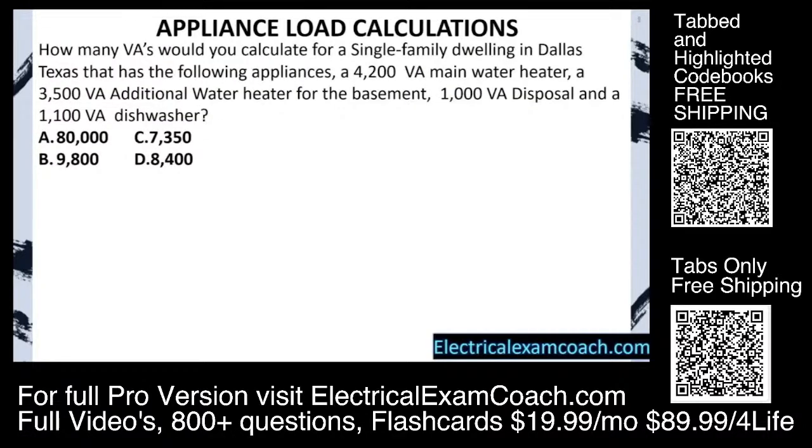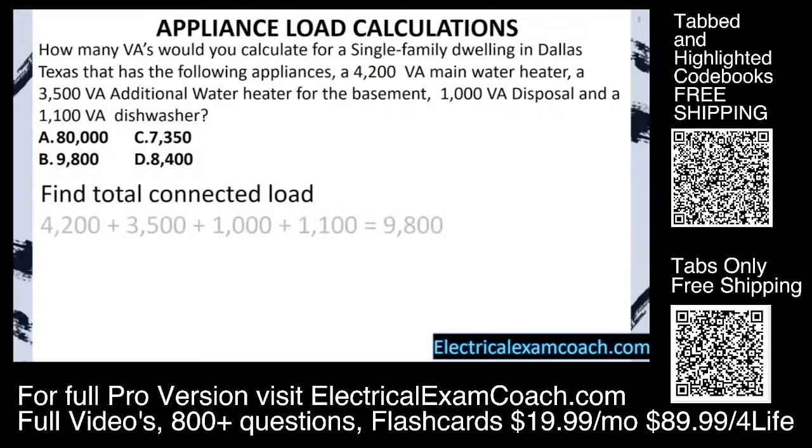How many VAs would you calculate for a single family dwelling in Dallas, Texas that has the following appliances: a 4,200 VA main water heater, a 3,500 VA additional water heater for the basement, a 1,000 VA disposal, and a 1,100 VA dishwasher? First, we're going to find our total connected load. We take and total it up, and it equals 9,800.